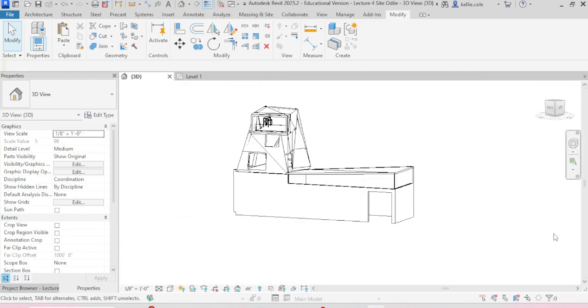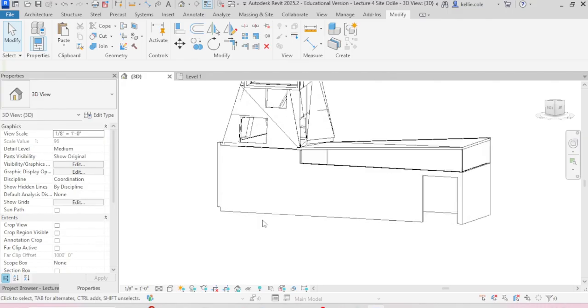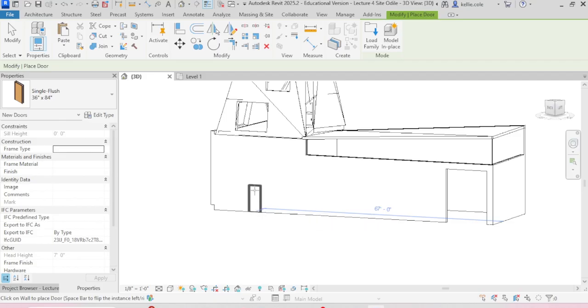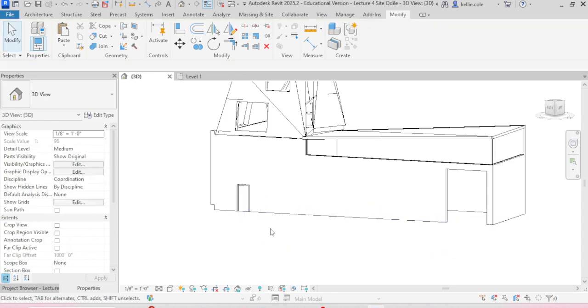On your own, I'd like you to insert all wall openings, doors, and windows by referring back to the plans and the PowerPoint at each level. You can work on your own. You're going to use 2 new keyboard shortcuts for door and window. To put a door in a wall, you simply use the keyboard shortcut DR and then hover. The door comes up automatically. Hover the door in the wall you'd like to locate it. The window tool is WN.